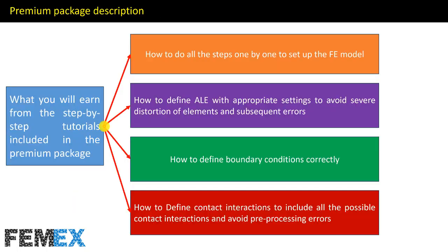What you will learn from the step-by-step videos included in the premium package of this tutorial. How to do all the steps one by one to set up the FE model. How to define ALE with appropriate settings to avoid severe distortion of elements and subsequent errors. How to define boundary conditions correctly. And finally, how to define contact interactions to include all the possible contact interactions and avoid pre-processing errors.